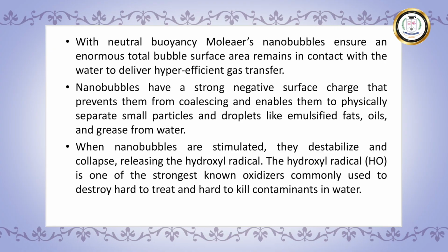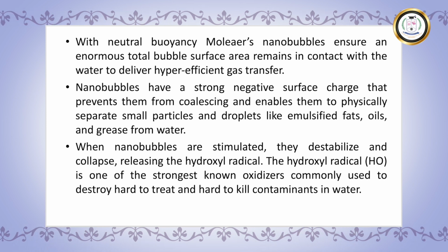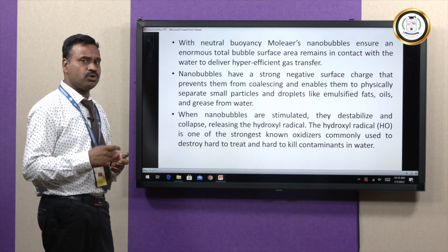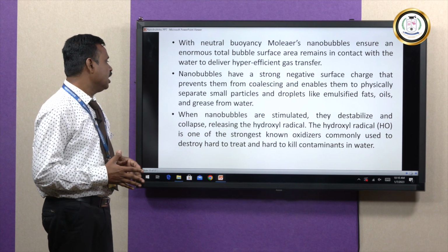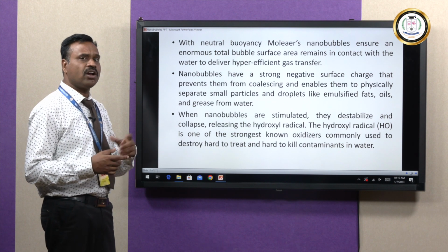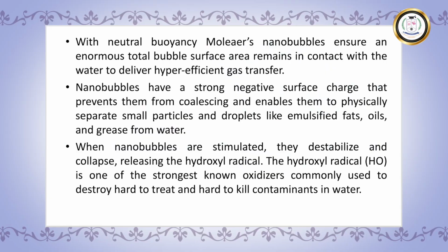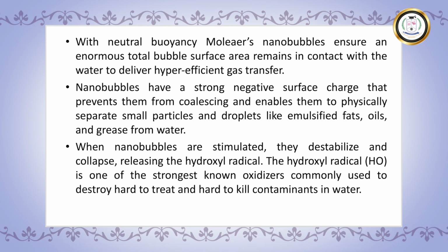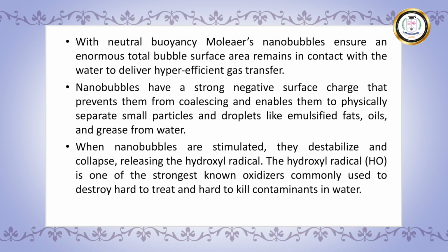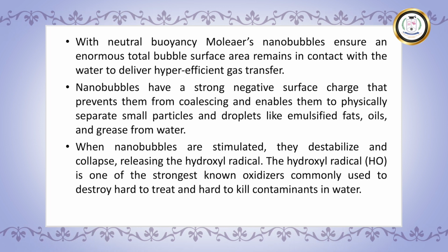And when nanobubbles are stimulated, for example, they destabilize and collapse. That is the one problem. They should not get stimulated. At that time they will release the hydroxyl radical. This hydroxyl radical is one of the strongest known oxidizers, contributing to killing bacteria and viruses, and breaking down all the pollutants, so-called contaminants, present in the wastewater.